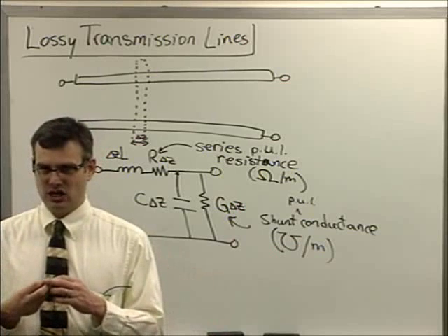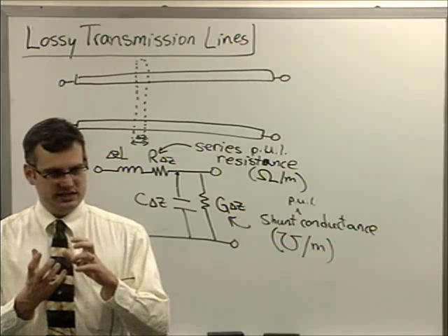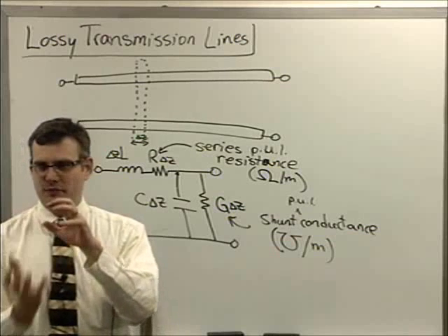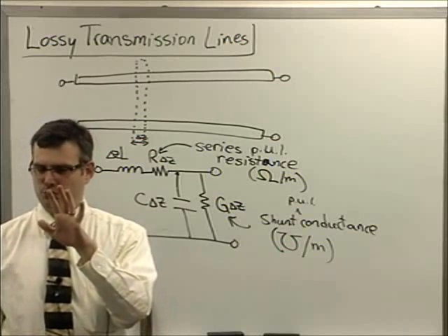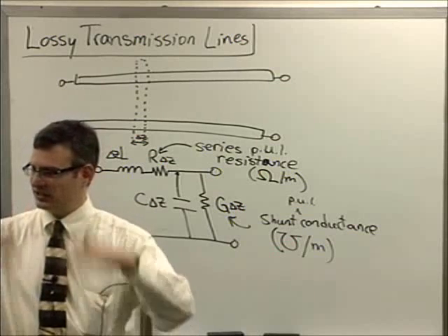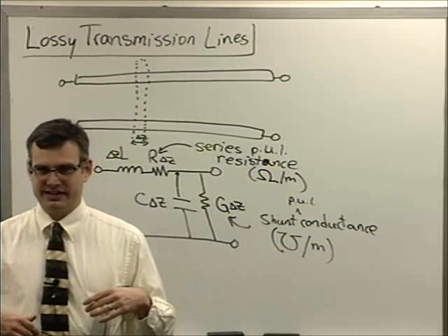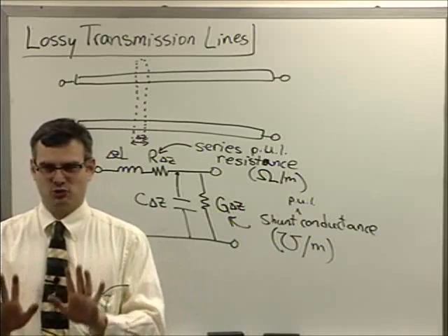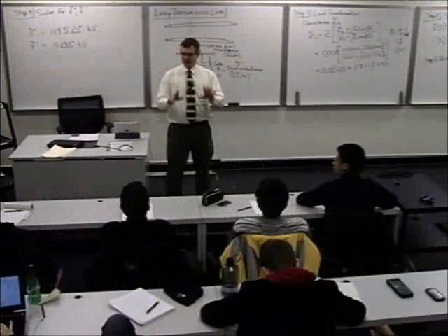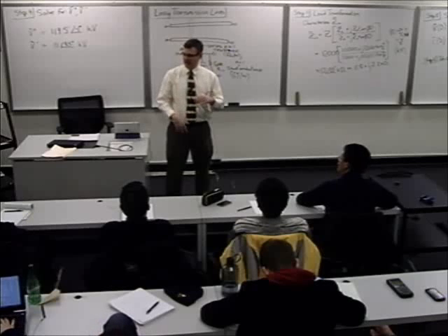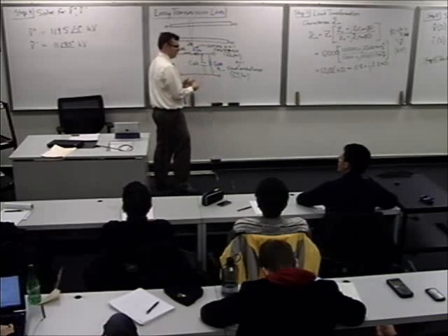Dielectrics can become lossy because there's literally a time lag between the excitation and deformation of electrons around a molecule, and they're springing back when the field is reversed in an oscillating field. As a result, it becomes kind of like pushing a child on the swing out of phase, right? You get a ticked off child that absorbs a lot of energy instead of swinging higher if you don't hit them on the right phase. So that is a mode of loss.